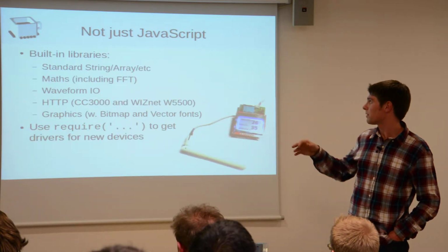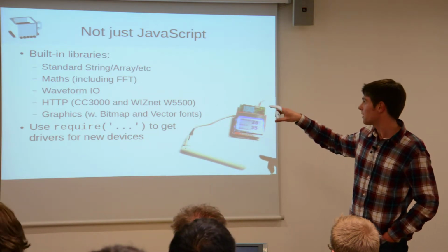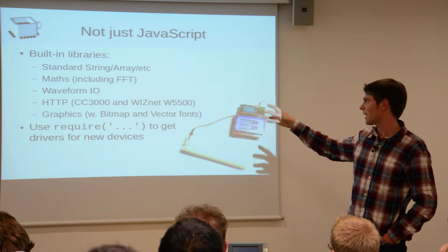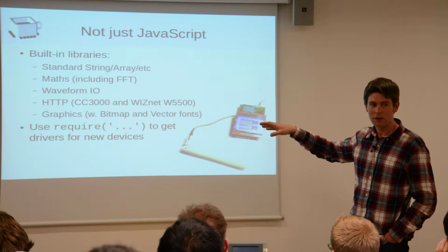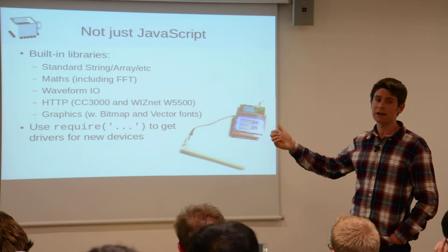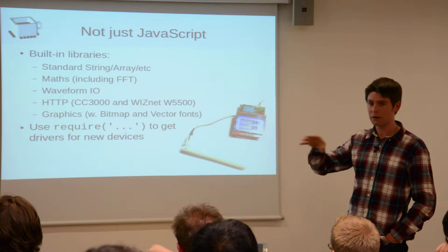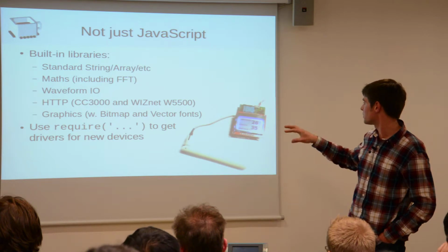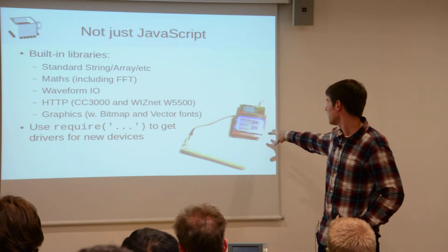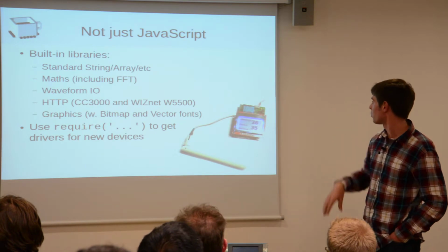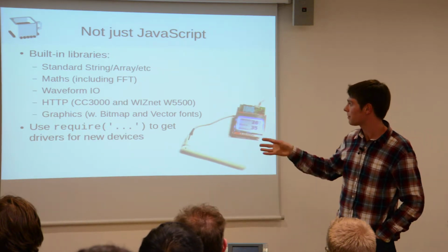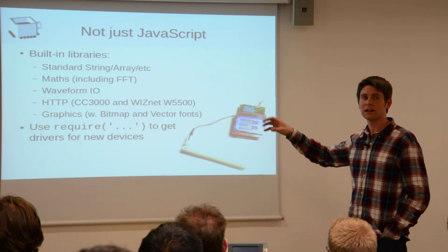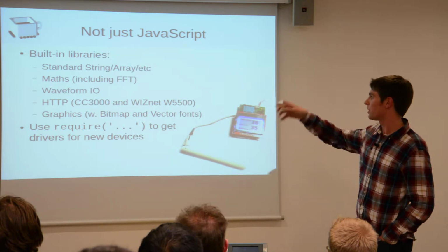And it's not just JavaScript either, it's got some built-in libraries, some of which are standard JavaScript ones, like array, string, maths. But then there are a few extras like FFT to read and write waveforms so you can do sound. There's an HTTP client and server based on Node, so it's almost code compatible. And the graphics library, with vector fonts, which is a nice side thing, because often you have a display like this and you just want to size the font to fill it. If you don't have something, you can just type require, and the web IDE, which I'll show you in a bit, will automatically detect that. It'll load whatever you said off the internet and load it into the device.